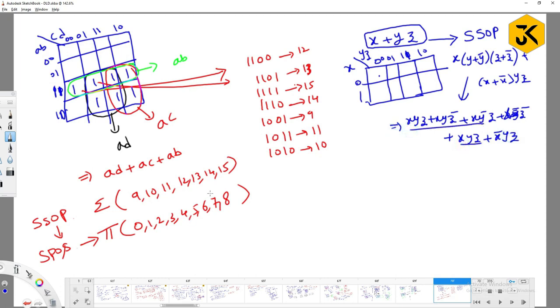That's it. Right? So if you would like to represent anything in the form of K-maps, compulsory those should be in the form of standard sum of the products or standard product sums. That you have to remember, right? Now what is the value of this one? This value is 1. This value is 1, right? So you can remove the redundancy. XYZ is redundant, XYZ is redundant. I can take out 1 because A plus A is A.